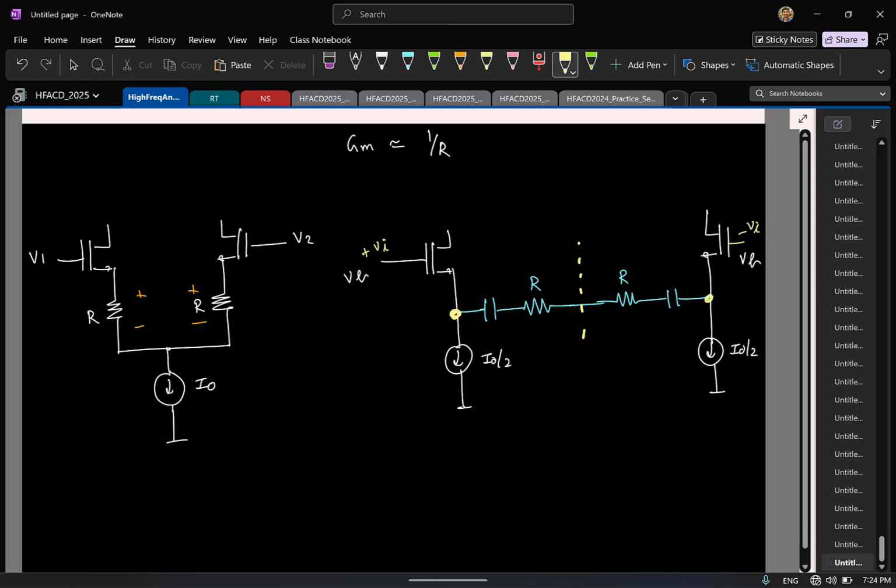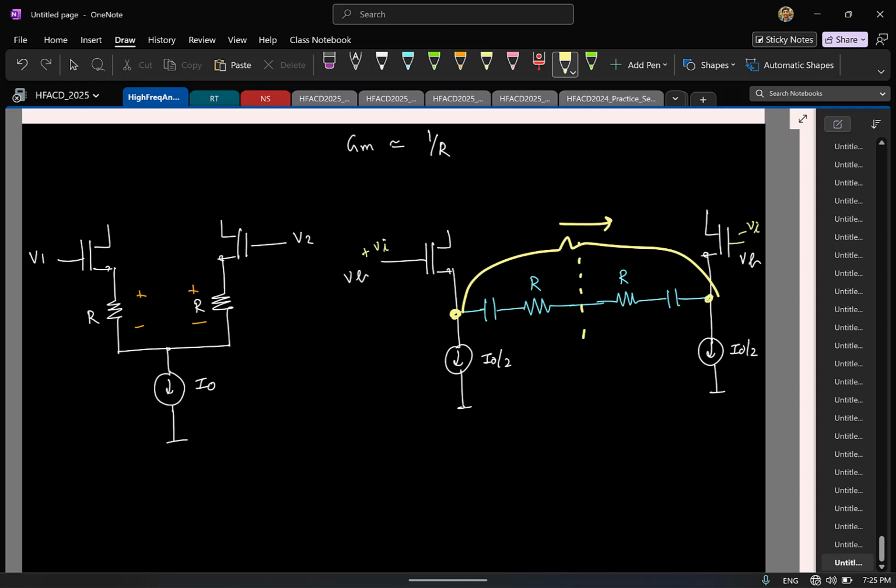They will be same. If the two voltages are same, even if I go and connect a resistor directly across this, do you think there will be a DC current flowing? No. So which means, do you think the capacitor is needed now? Not needed, right? So you can actually remove the cap and directly go and connect it like this.